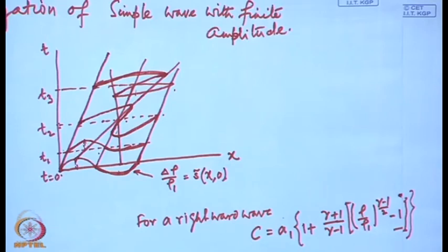Now, in the compression part, the isentropic relations are valid until the diffusive actions are considerable, or until the viscous friction and heat transfers are important. When the stationary balance between diffusive actions and the nonlinear steepening effect is reached, the conditions across this wave front are given by the shock wave relations, which we have derived earlier.